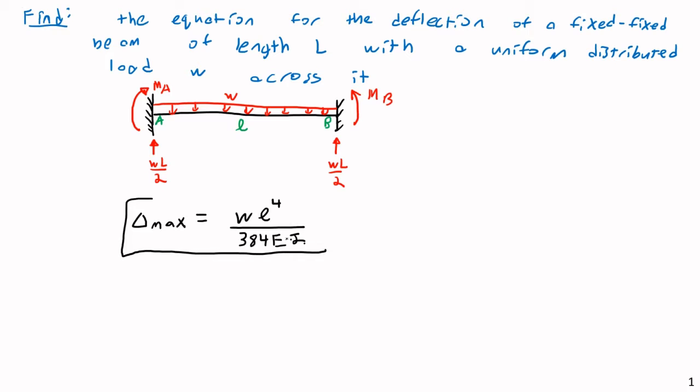And our entire discussion today is going to look at where these equations come from. So we see these equations for bending, or equations for deflection, in various places. And in the case of statically determinate beams, it's very easy to derive those using the methods that we've looked at throughout the entire semester. But when we look at statically indeterminate systems like this fixed beam, then it can be a bit more challenging. And we need to use some method like the force method, the slope deflection method, sometimes virtual work, other methods, etc., in order to find an actual useful equation.